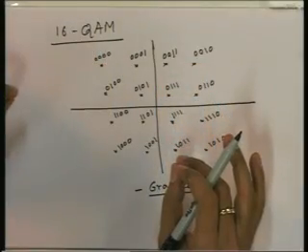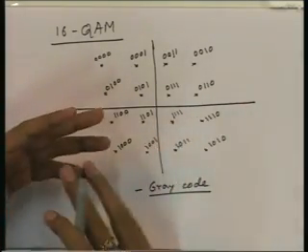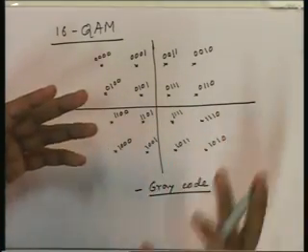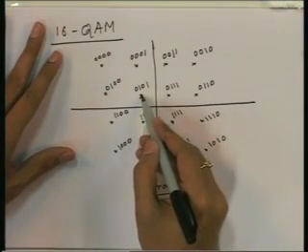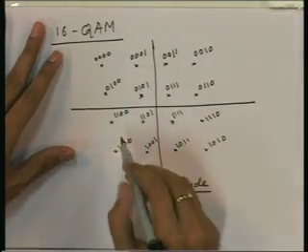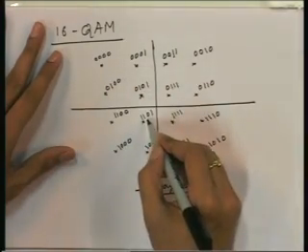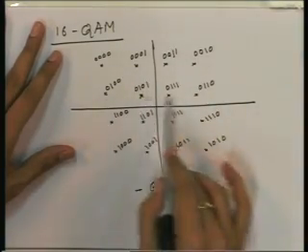So, that is again nice, because that will ensure that whenever there is some error, there will be only 1 bit error. So, one symbol error will most of the times result in only one bit error, because most of the times the error will come because if you transmit this, most of the times you will detect a neighboring point instead of that point. So, these 4 are the neighboring points, and there will be only 1 bit difference between these points.